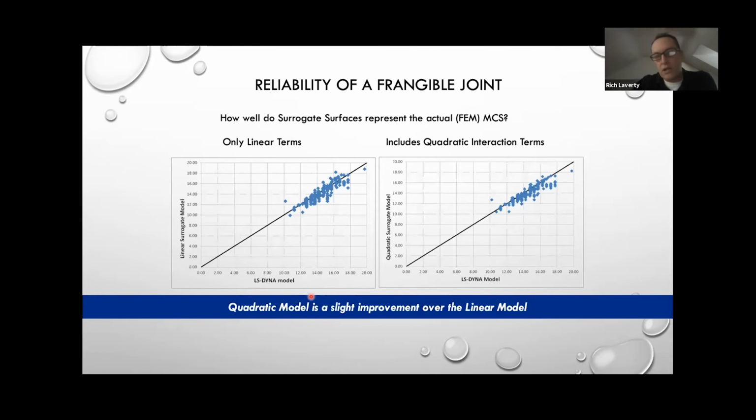But we have to be careful how we interpret the results, because this is an approximation of the finite element model, which is an approximation of a laboratory specimen, which is an approximation of an actual joint. So we're removed many levels from quantitatively telling you what the minimum charge size is. The usefulness is that I can randomly generate designs, 1,000,000 of them easily, and evaluate the minimum charge size, and then identify outliers. So I can find designs that would be predicted to do really bad.